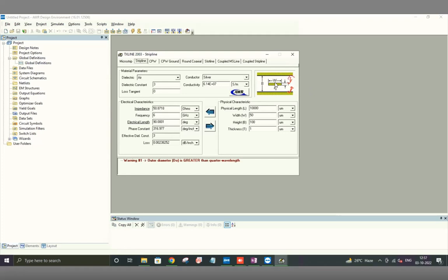So there's capacitance now from both sides, right? There's a capacitance here, and because these two are both ground planes, we assume that they are at the same potential always. That is an important assumption. So if the center conductor becomes smaller in width, then the capacitance will also go down.